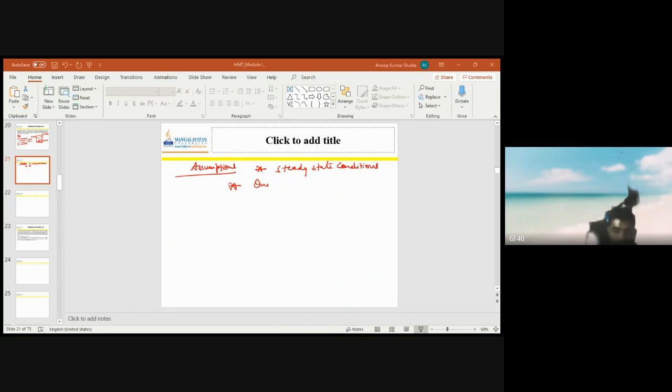So these are the values of heat transfer coefficient for some fluids like air, water, vaporization of water, condensation of steam. So for atmospheric air, when free convection is used, the heat transfer coefficient varies from 6 to 30 watt per meter square Kelvin, and for forced convection, we have taken 10 watt per meter square Kelvin, and for free convection in the case of water, it varies from 500 to 1000 and so on.